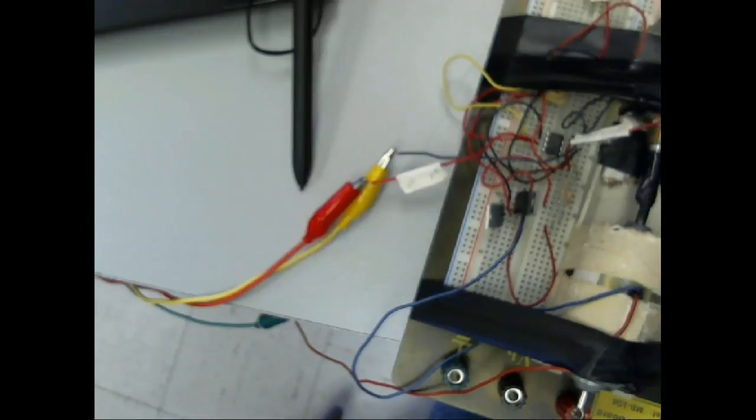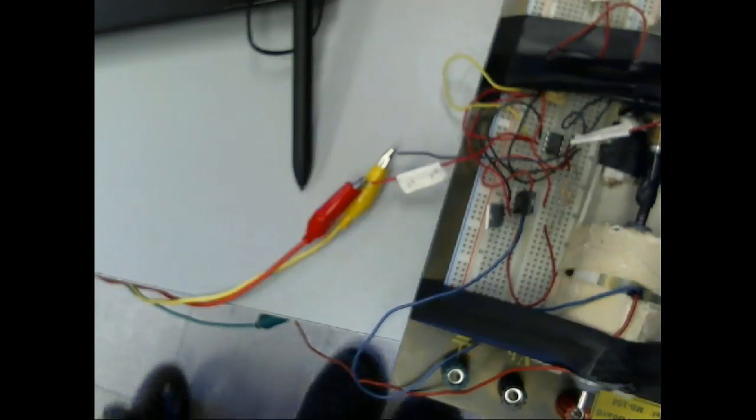What we like to do is when it starts approaching it, instead of just going wop, wop, wop, which is what we're doing with proportional control, is to level it off. And the closer it gets to the set point, we start leveling off. And instead of coming in like this, we come in like this, which gives us a lot better control of it. And those are called I controllers, the PI. So we combine them. A PI controller, we combine them and we could get rid of that. But we'd have to add a little more stuff. We'd have to add an integrator to it.